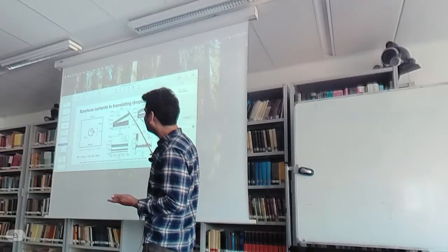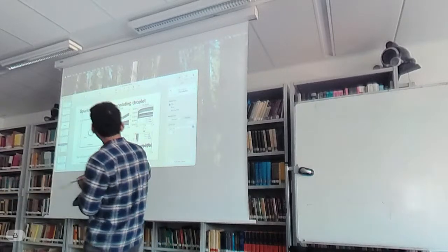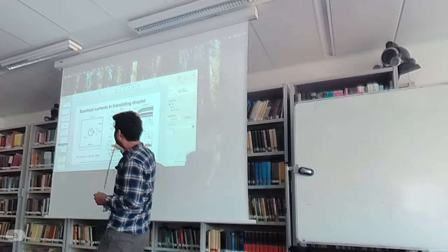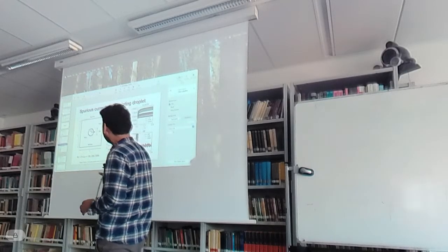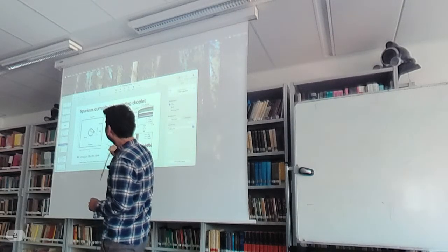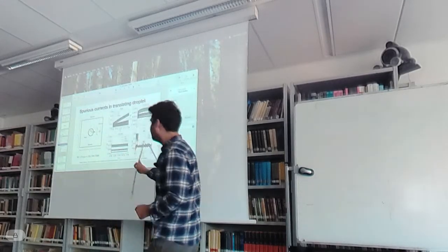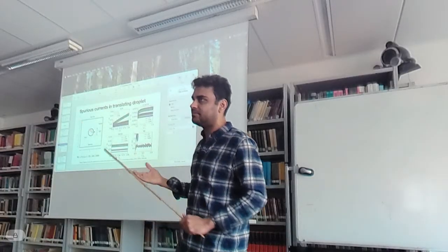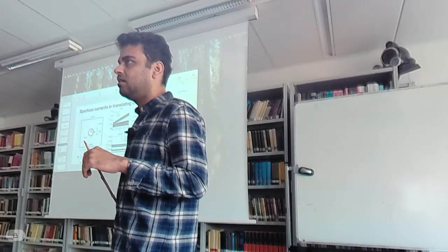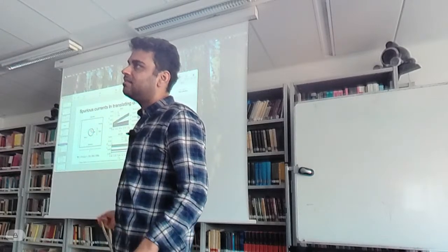Whereas in this case, you can see the spurious currents. So this is the CSF method, this is CLSVOF. So in CLSVOF, it's already less as compared to the CSF method, whereas in HF2D it's larger, but then they grow in this method, they don't grow in this one. And then in HF it's really bad, the spurious currents grow very quickly to very large values. Yes, assuming a static interface, CSF would be better.